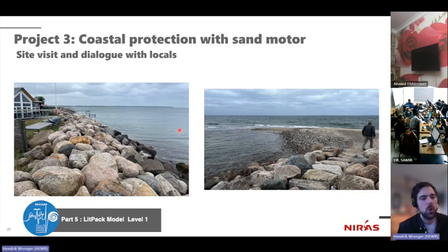So here we have no beach left, right? We discussed that. This is a longshore structure, and if the stone sizes are designed correctly for the wave events that we can expect here, then this is a non-erodible component in terms of sediment transport. And then this is the tip in the south, a very dynamic sandbar that extends southwards and changes appearance all the time.